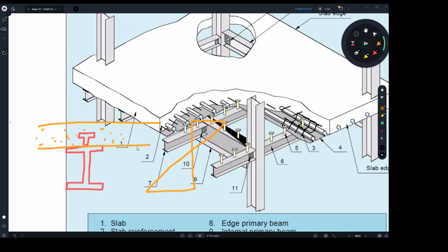Wherever we're straining the concrete, we're going to be straining the steel. So that's the point. We need to make sure practically we have managed to interlock the two materials, so they're going to be strained together. They're going to be deformed together. That's maybe the easier word. And if you manage to do this physically, then your section is composite.